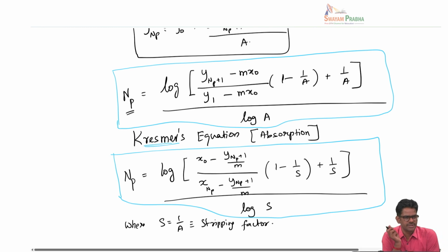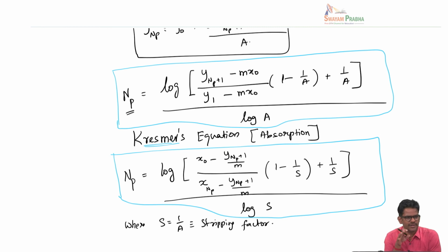So this Kremser equation is very important because if you look at GATE questions on absorption at a tray column, pretty much entire questions actually come from the application of this equation, because it's an analytical result. Very rarely you get graphical questions, and it's not that you have to memorize this. Generally these equations are actually given. You have to know how to use this equation, that's all. Sometimes this absorption factor A may not be given, that's something you have to calculate. Otherwise pretty much it's more like a substitution and get the answer.